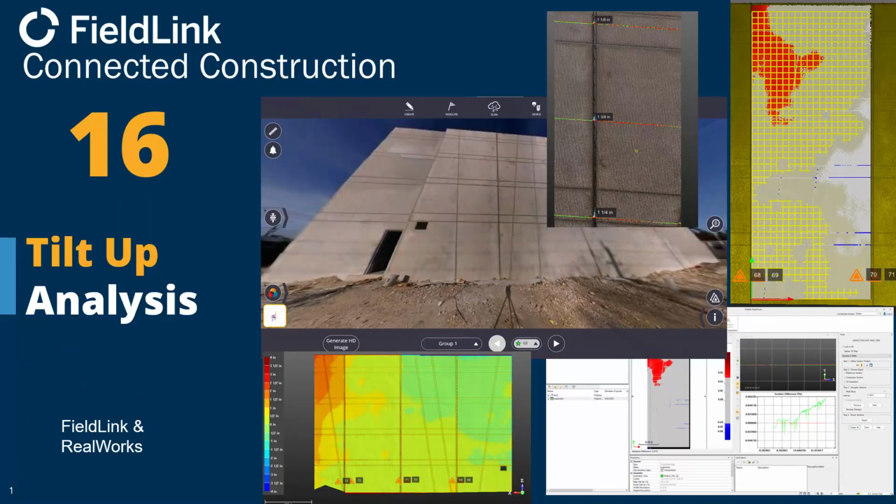This FieldLink tip number 16 is going to be ACI tilt-up analysis. You can make sure that your walls are within spec. We're going to be using FieldLink to do some in-field workflows as well as some deliverables created from RealWorks. As you can see here, this is the wall we're going to be analyzing, as well as some of the gap analysis we'll be doing between the panels, verticality over one, over all of them, and then show you some of the other deliverables we can create.